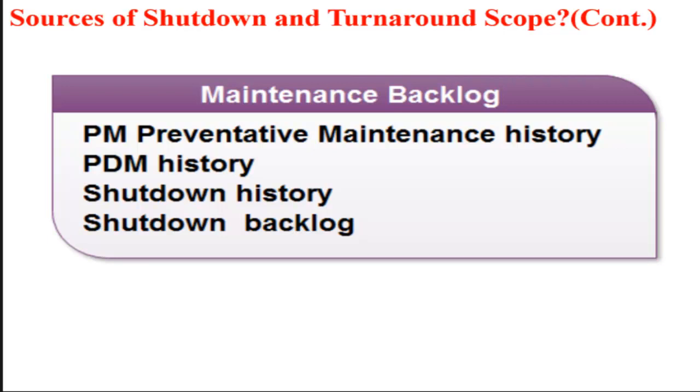Of course, backlog can cover different types and categories of maintenance, including time-based maintenance and feedback coming from time-based inspection and the PM inspection. Sometimes PM feedback reveals problems, and these problems might not be able to be executed during operation time, so they are set aside for turnaround.